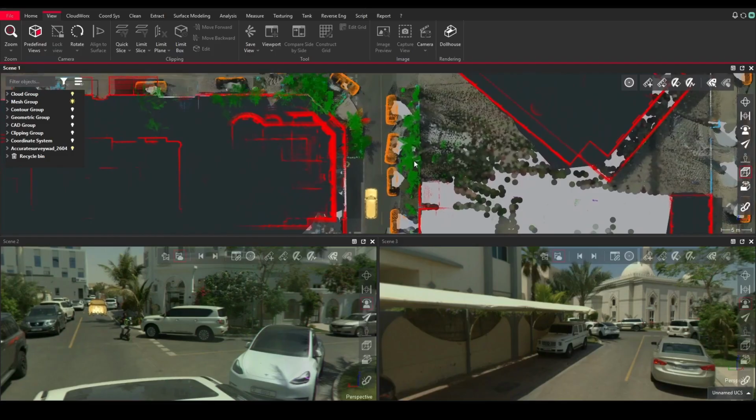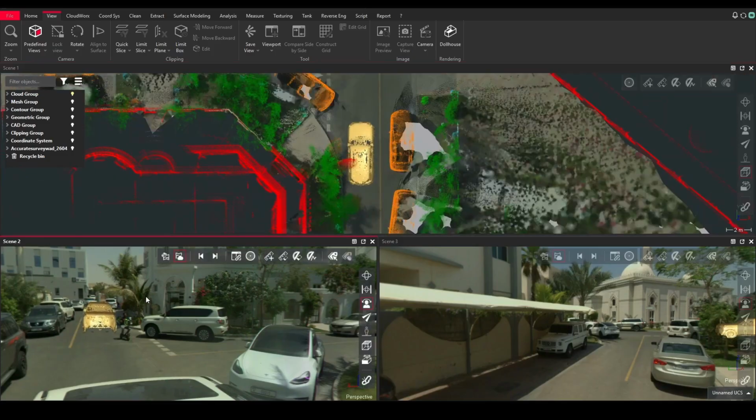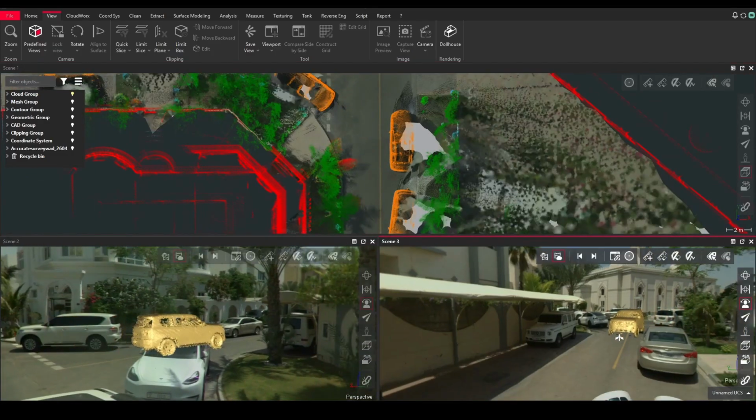Second method for vehicle trajectory. The second method is ideal for simulating vehicle movement. Before running the script, you need to prepare 2 key elements in your scene. The first element is the trajectory of movement. This is a polyline representing the object path.